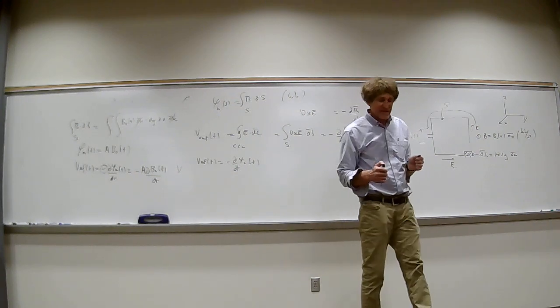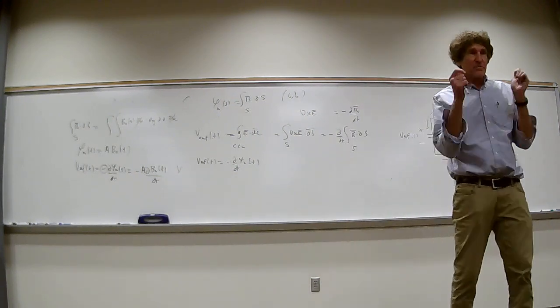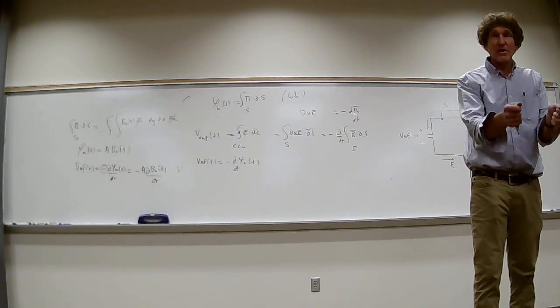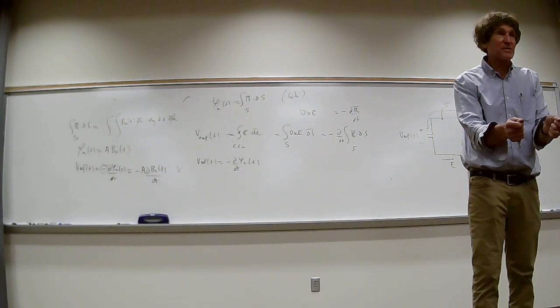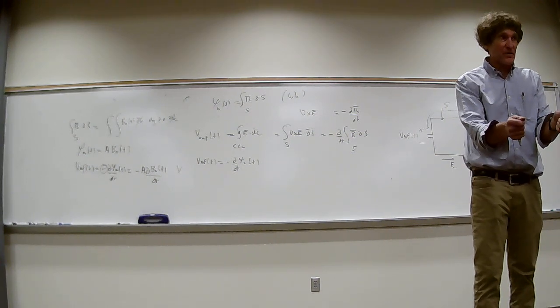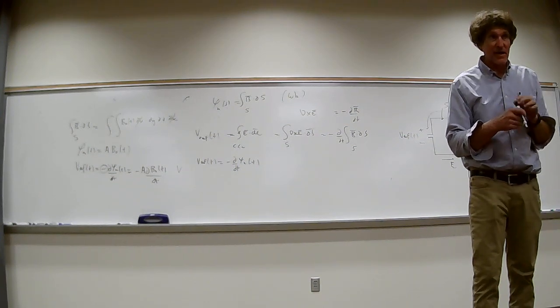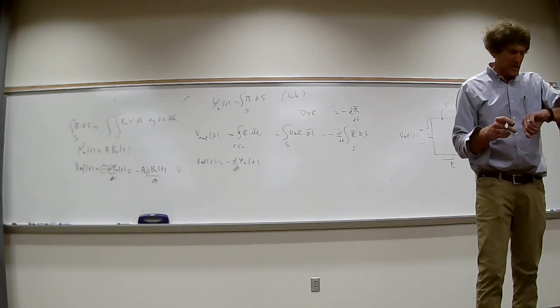Everybody, I'm trying to make this clear to you. You've had meters, right? Everybody has used meters. If you take a meter and put it on a car battery and you put the positive lead on the negative terminal and the negative lead on the positive, you read negative 12 volts, right? That's what I'm trying to say here. The polarity is important, okay? And you'll do some problems with this in mind.